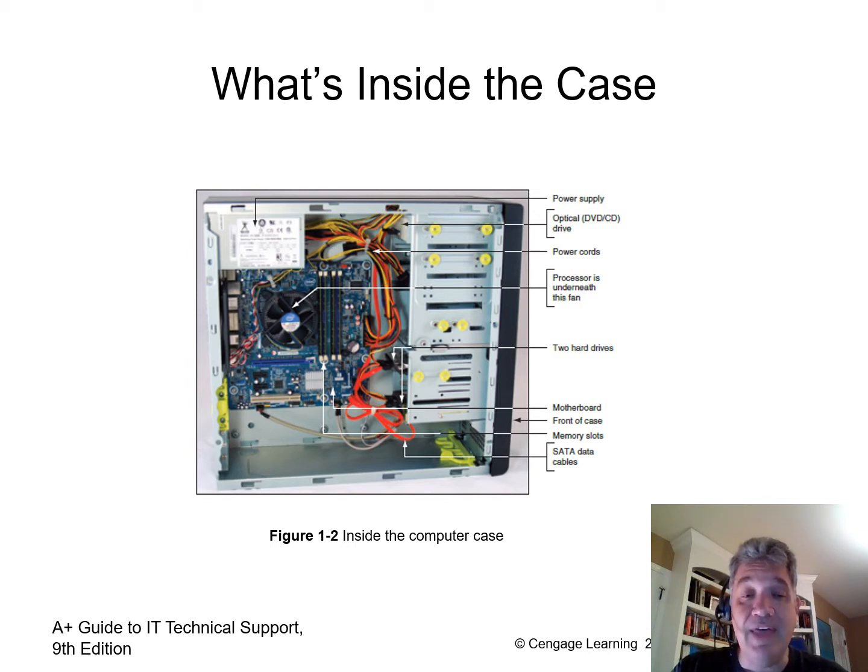One exception to that would be if you've got a low power handheld battery operated vacuum, perhaps one with a small brush like you might use to clean a keyboard. That's probably safe for use around a PC or a laptop that's open, but you certainly don't want to use a vacuum cleaner that you would use otherwise to, say, clean your floors or a shop vac. Much too powerful and can generate a sizable electric charge.